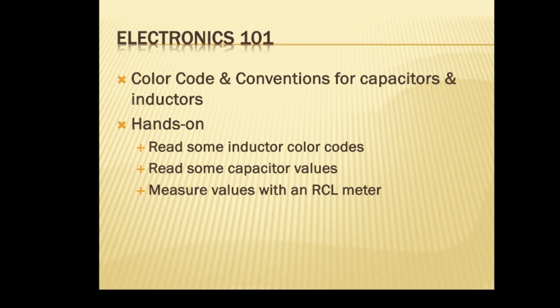Okay, I had a good question just came up there. How do you tell if it's a resistor or an inductor? Because the colors are the same. I mean, red is 2 and orange is 3 and yellow is 4. It doesn't matter. You can measure with an ohm meter, or like in the case of the resistor we were talking about, that resistor is 470K ohms. You're not likely to see 470K or 470 millihenries, especially in a tiny inductor like that. Possible, yes, but likely, no, it's not likely at all.